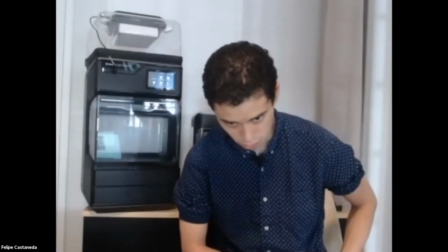Okay, that's good to know. Another question on the model itself: how do you change the reference or origin point of the 3D body? So before exporting, you can simply move the body away. We have one origin point in the workspace, and each body is oriented around it, like in a multi-body model workspace.